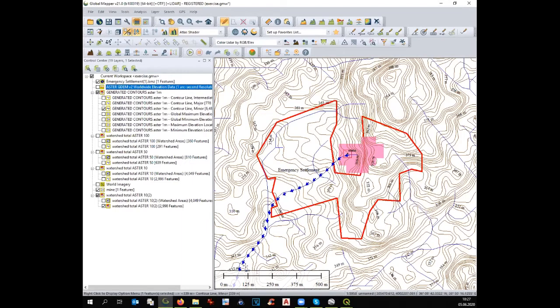Thank you. The problem here is that the digital elevation model that we use is not very precise. And you know, with water, you need to be very precise. That's why it's important to go with a total station and to make a proper survey, or even better and easier and cheaper, with a drone. Do you use the drone for your project? No. No, okay. I use the drone. I might, at the end of this workshop, come with drones to use.